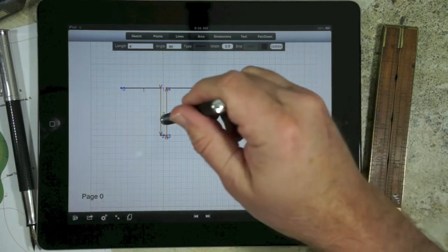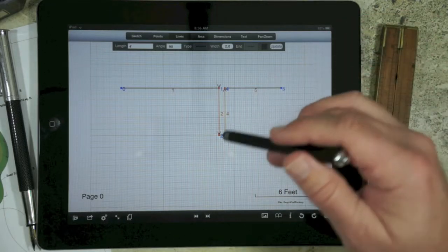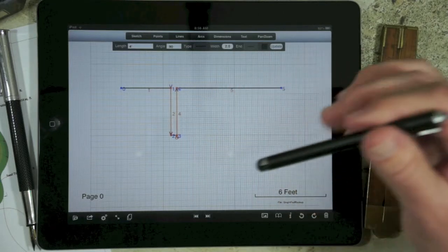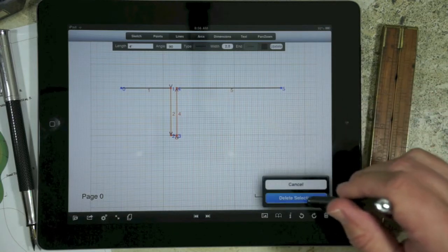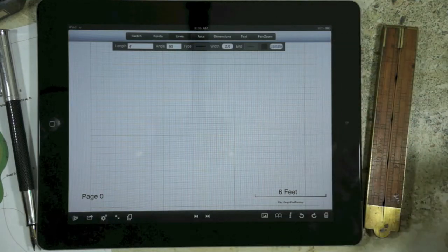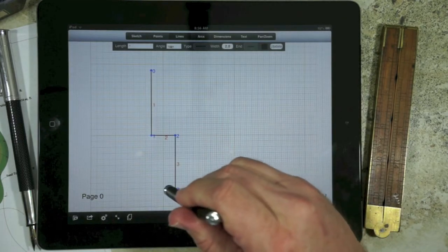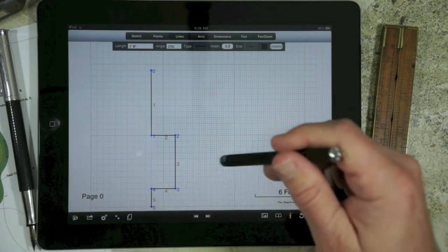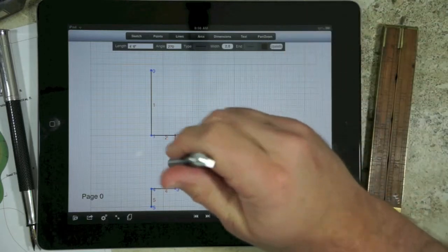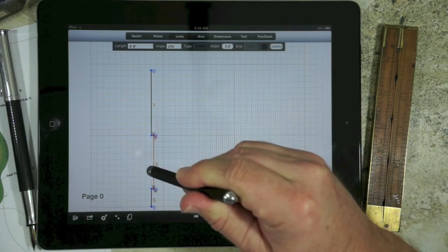So that brings out a very important point in that when we're trying to define a very precise geometry, it's easy to offset everything a long distance and then move it into position rather than trying to move it a very short distance. So that's very important when we're creating, say for example, a long wall with a bump out. To do that, you draw the larger dimensions and you bring that spacing out quite a bit. Say this was only a 1 inch gap or a 1 inch extension, if we grab that line, we can now move it in to where it's a very small distance and still retain our accuracy.